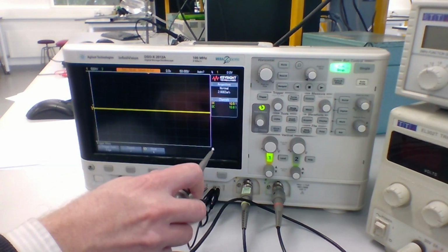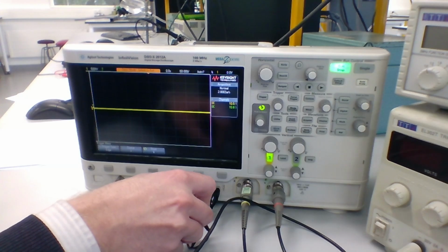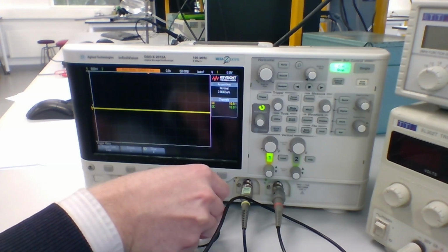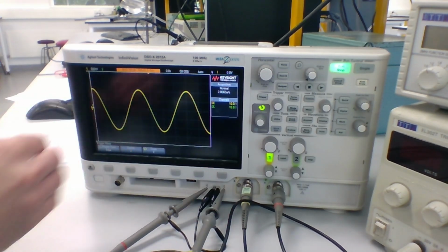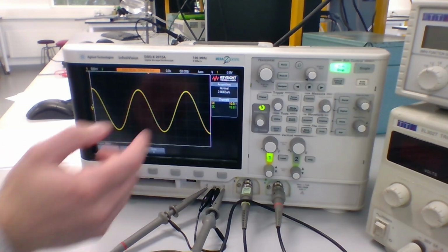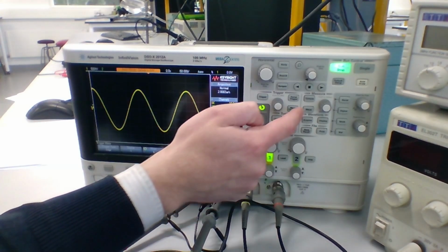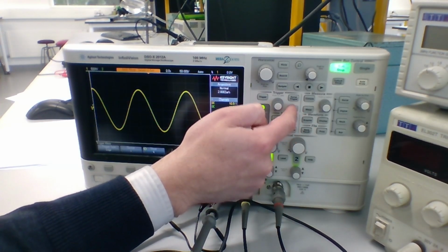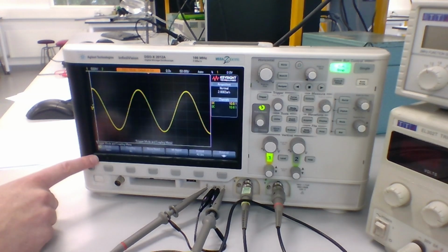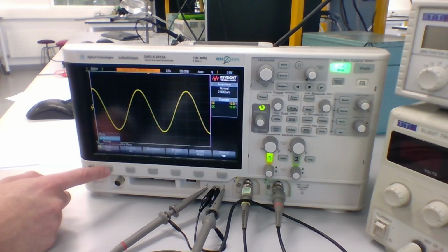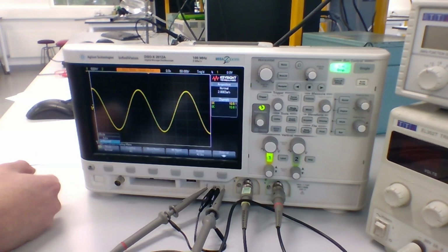We first of all hook this back up again to see what happens. So in auto triggering mode, which we're now in, if we disconnect, the screen clears. When we reconnect, it takes a measurement again. We can change what triggering mode we're in if we press the button labeled mode/coupling. You'll see on the left hand side, it currently says mode is auto. If I press that, I can change that to normal triggering.